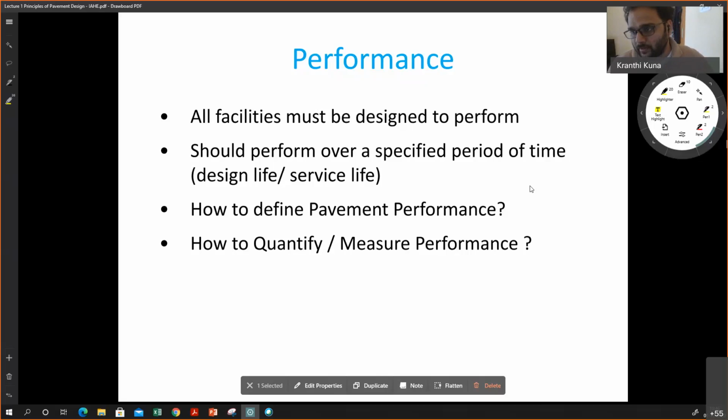Concrete pavement may last for 40 years, bituminous pavement may last for fewer years, but concrete pavements are difficult to recycle, whereas flexible pavements are relatively easy to recycle. So basically it comes to life cycle cost, but obviously decisions at higher levels dictate what happens in practice. If anyone wants to answer that question on my behalf, you can, but my answer is that it is very difficult to answer, but in theory it should be based on life cycle cost.